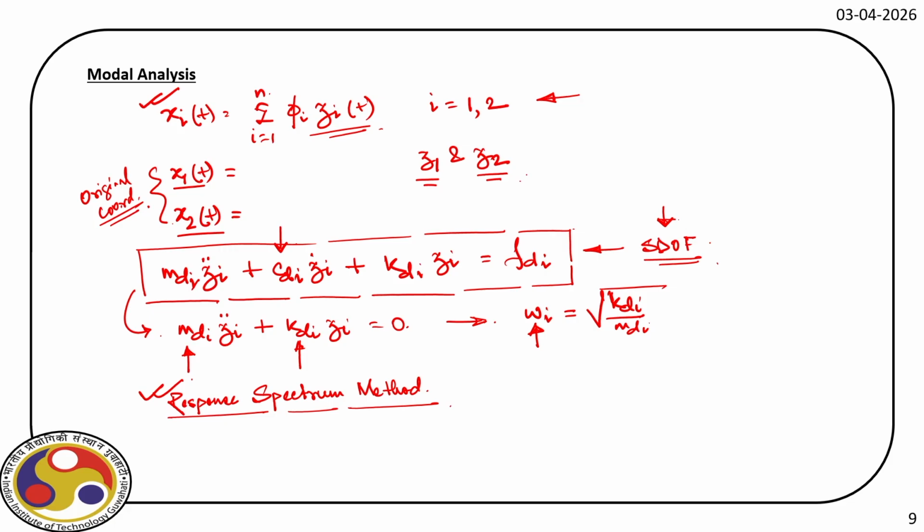We applied gravity load. From there, we identified the reactions also, if you recall, the support reactions. But today, first we have to define the mass of the structure, and I will show you in a minute how we can do it in STAAD.Pro. So now let us move over to STAAD.Pro.